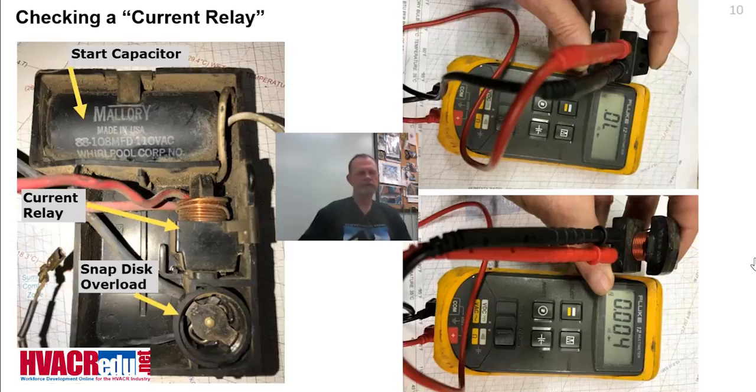I wouldn't say that's a good idea. I'd say go down to Home Depot and get the right one. What is a circuit breaker? A circuit breaker is there to protect the wire. It's not there to protect the load. And unless you know what the amperage capacity of the wire circuit is, that could be a problem. So, yeah, go to Home Depot. Get the right one.